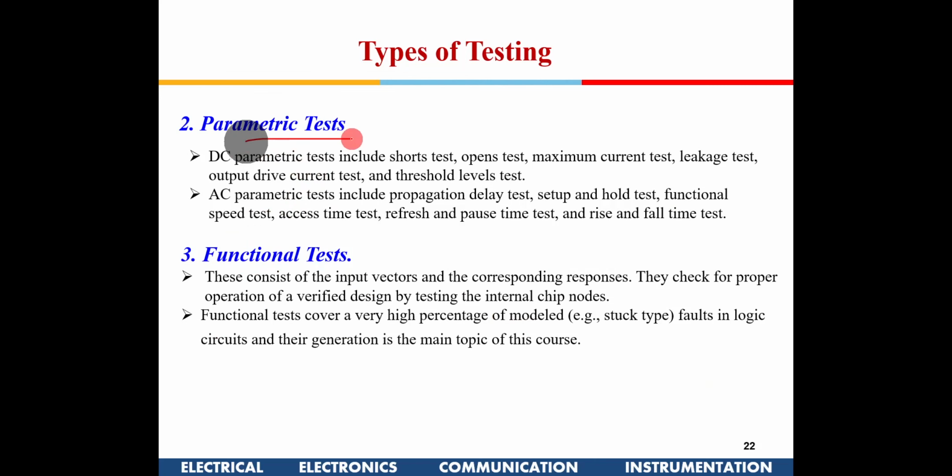Then there is some parametric test, which includes a short test, open test, leakage, and all things. This also can be done. And then functional test, which is for the proper logic. So some limited amount of functional test can be done post fabrication, not an exhaustive check.